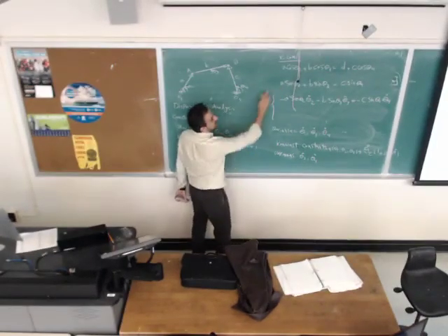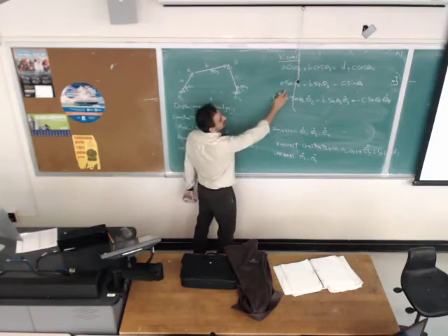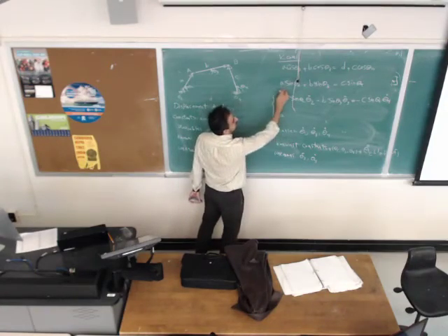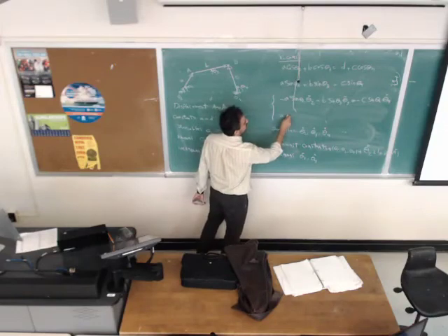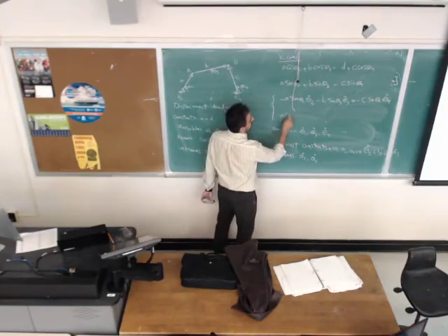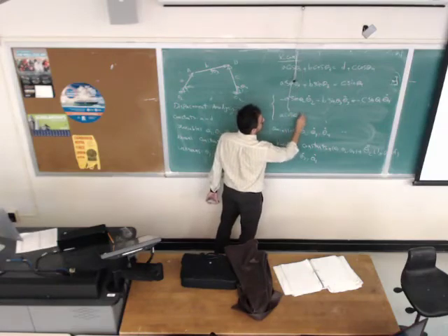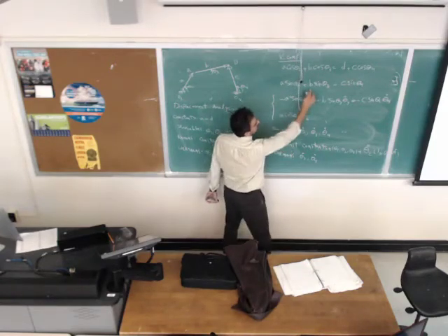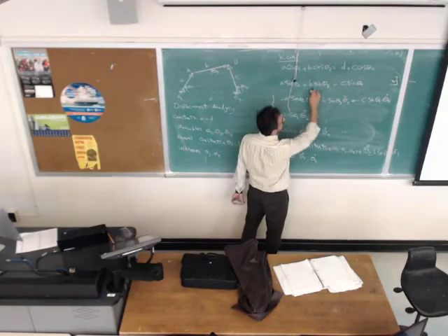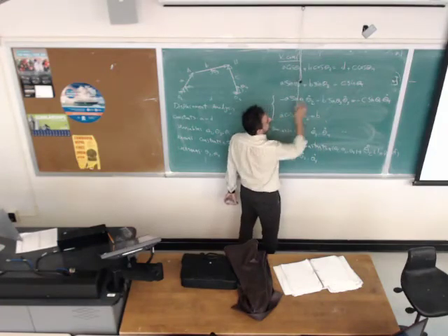For the second equation, I'm going to get the velocity equation. The derivative of a sine with respect to time is the derivative of sine with respect to theta 2, which is cosine of theta 2, times theta dot 2, plus b times the derivative of sine with respect to time.